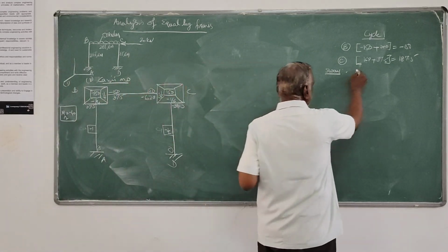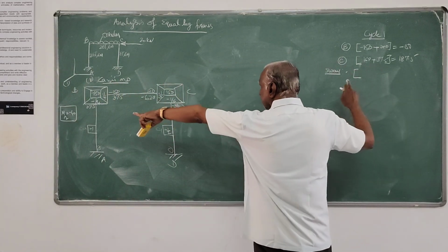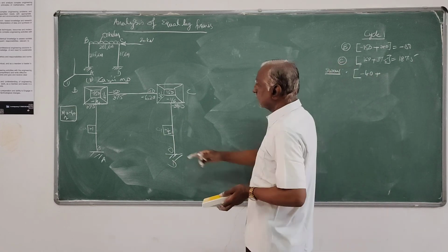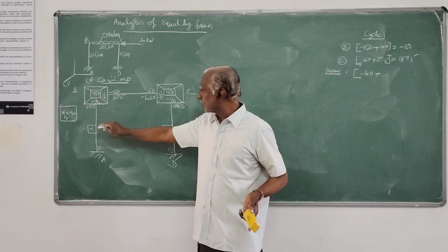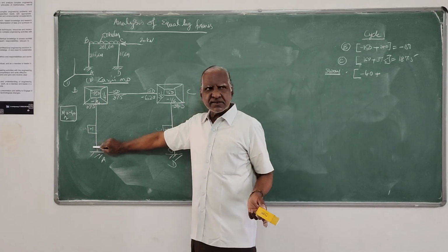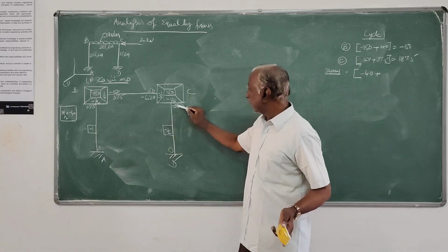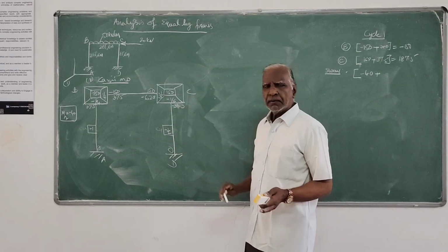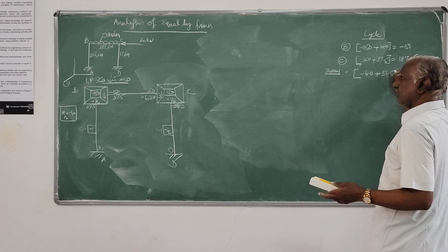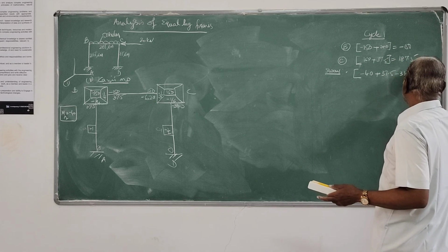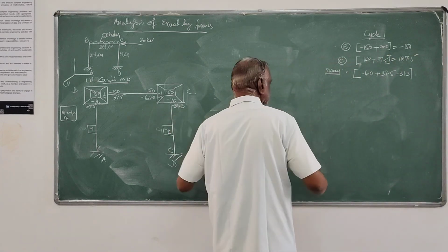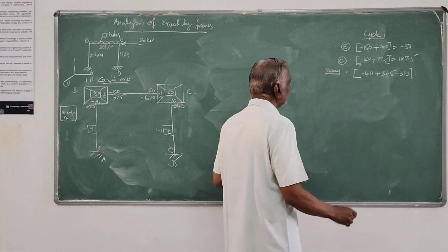Only that sum I will determine, that is MR. MR is minus 40 plus sigma MJK of rotation contributions, that is 37.5, here it is 0 for this column. Here it is minus 31.3 plus 0. So it is just 37.5 minus 31.3, that's all. So that sum I have to multiply by the corresponding displacement factor.